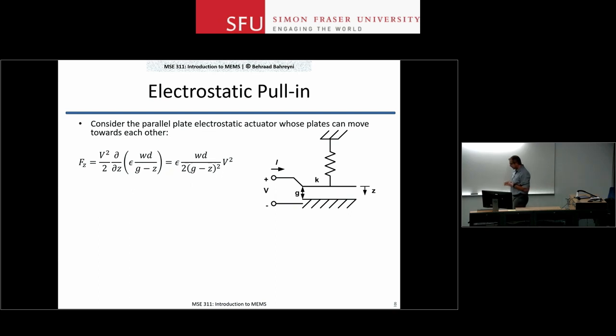Now the question is, what are the limitations of electrostatic actuation? Well, we saw that if you look at the normal force between the two electrodes, if the gaps are small, that normal force can be much, much higher than what you could get if the electrodes move past each other. You have a problem here because the dC/dy factor wasn't linear. If you go back and look at the formulas we had, you could see that dC/dy depends on the separation between the two electrodes at this point, right? So that nonlinearity can bother you.